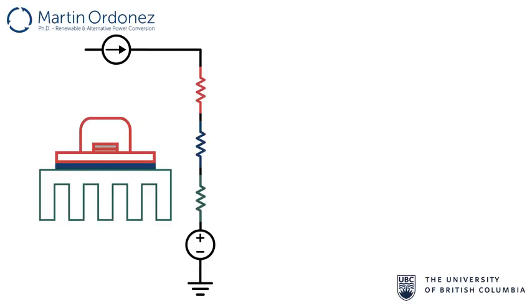A MOSFET is connected to a heatsink via a proper thermal conductor. The heat produced inside the MOSFET goes through the materials and then is dissipated by the heatsink. Therefore, we can define three different resistances between the junction of the MOSFET and the ambient temperature, which is taken as reference.